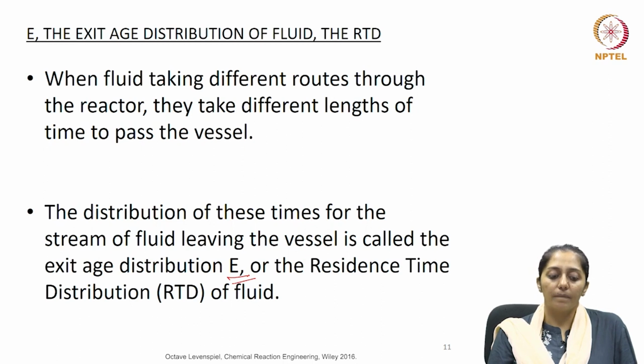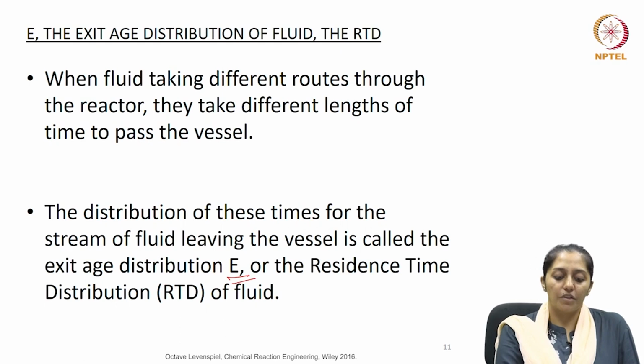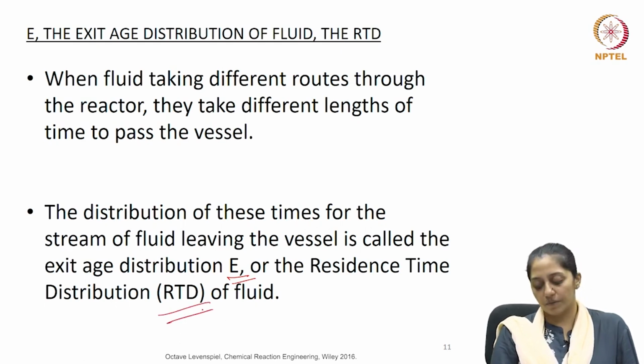So, I will repeat, the distribution of these times for the stream of the fluid is called the exit age distribution, denoted as capital E, which is the same as the residence time distribution. We generally call it the RTD of the fluid.